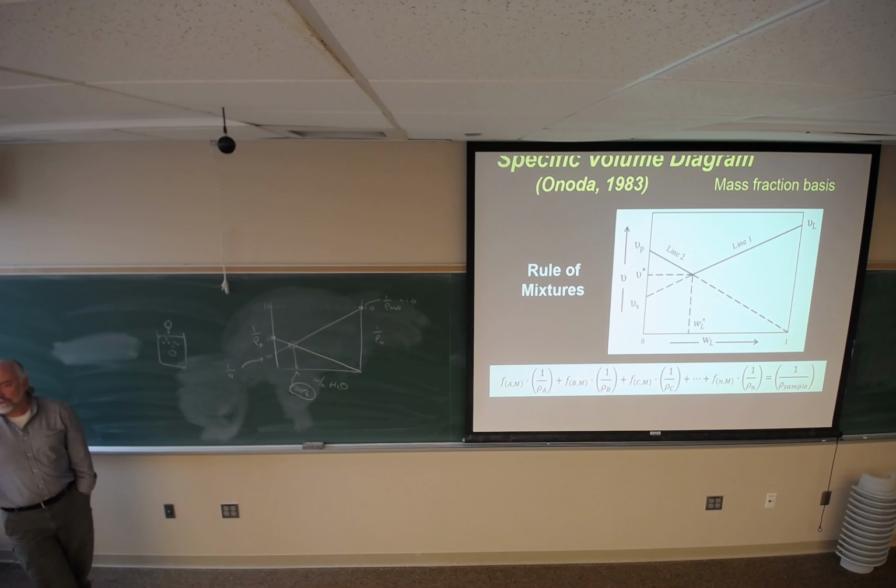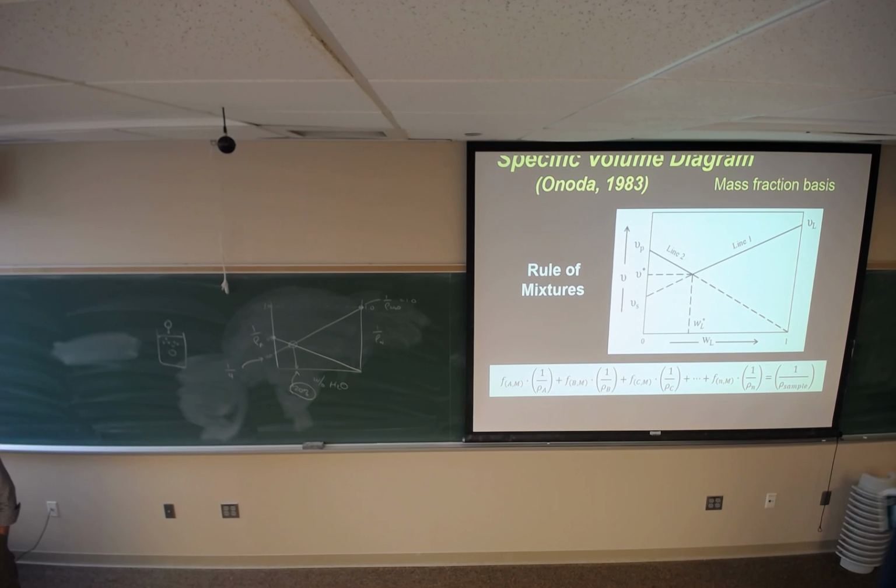Let me take it a different direction. You leave here and you go work for a company, right? They make ceramic components. Is everything they make out of alumina? No. What if I make it out of zirconia? What if I make it out of silicon carbide? What if I make it out of clay or porcelain, right? What happens is that the density of my powder is changing. Good? What's the packing density of zirconia? Good. What's the packing density of silicon carbide? Oh, you're good. Okay? So I call him because he says 50% no matter what I ask for some person.